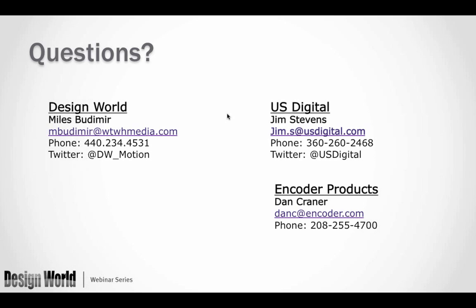Yeah. Well, just the shaft seal. Let's say, for example, we have one shaft seal that's at an IP64 rating, and the same encoder could have an IP66 rating. The seal material is thicker.